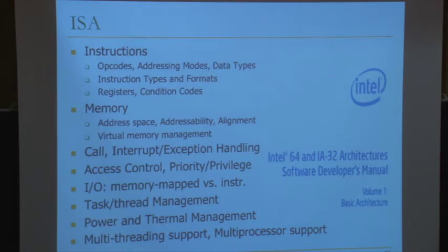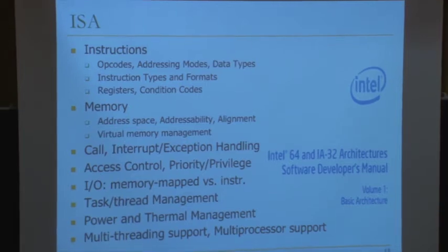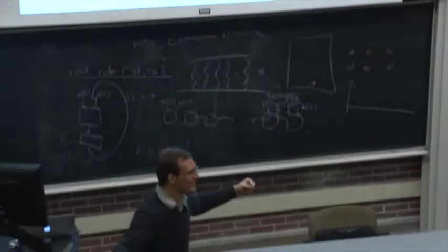Right? And the system programmer needs to know how to do voltage and frequency scaling. Right? This is exposed to the programmer. Although, do you have to do it that way? No, not necessarily. You could have a processor that dynamically scales the voltage and frequency without exposing that to the programmer.